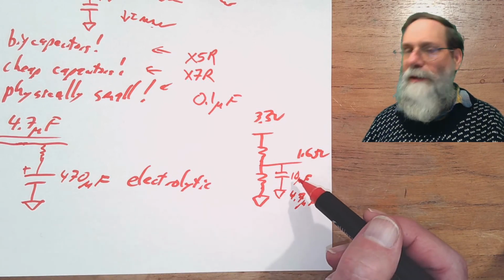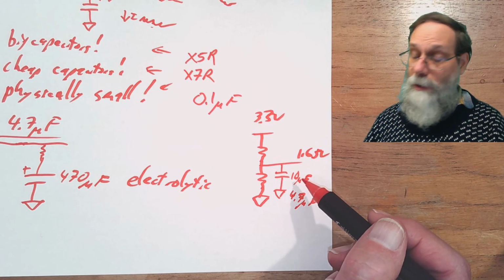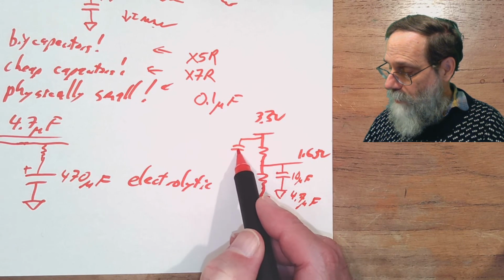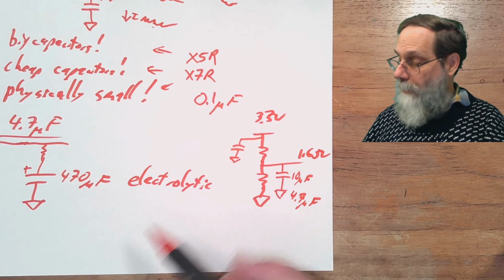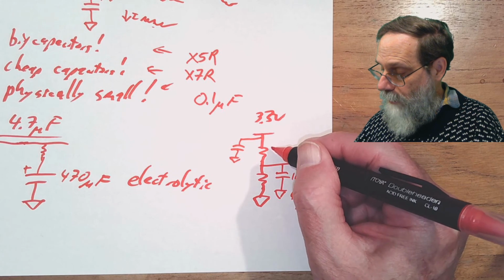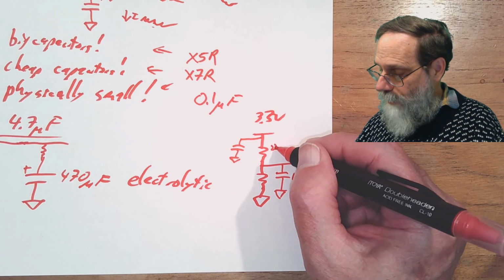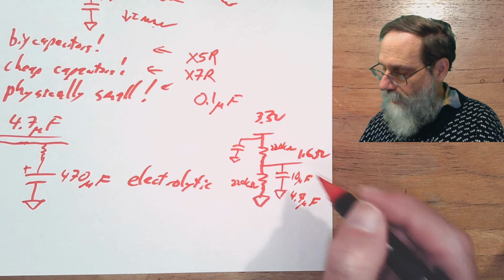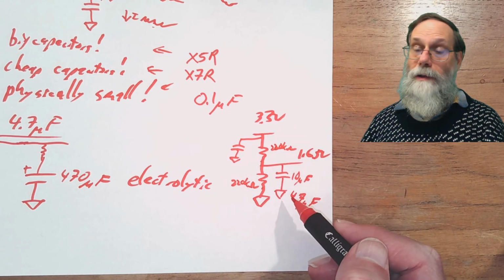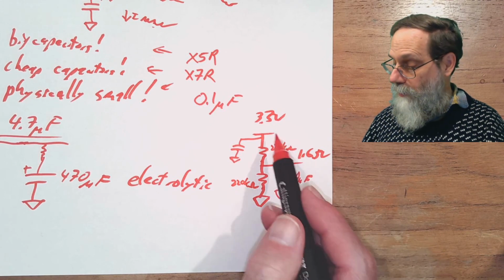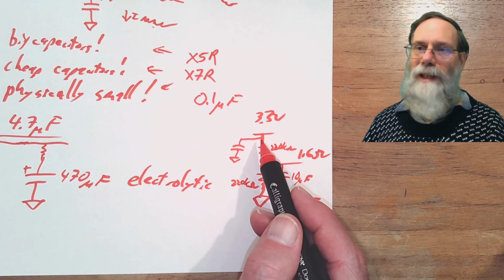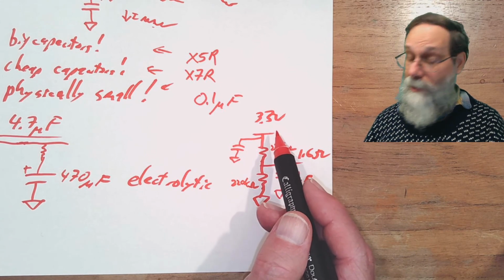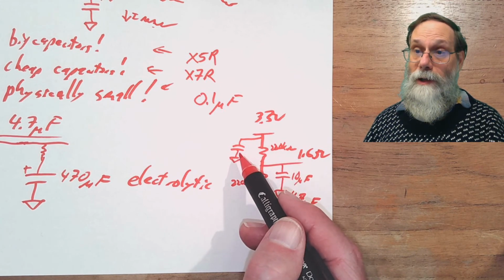And you can think of this as a bypass capacitor if you want. Notice that putting it here has much more effect than putting a capacitor just directly on the power supply, because I can make these resistors pretty big. I mean, these might be 220 k ohm resistors if I don't have to take any current. And then I've got a very large time constant for this thing, whereas this capacitor here has got only a few milliohms or tens of milliohms of wiring resistance,